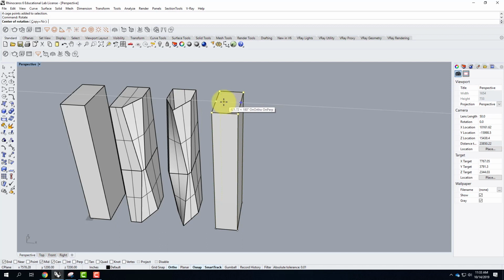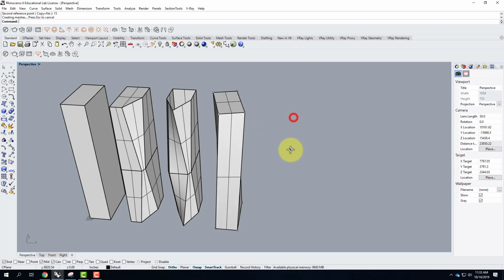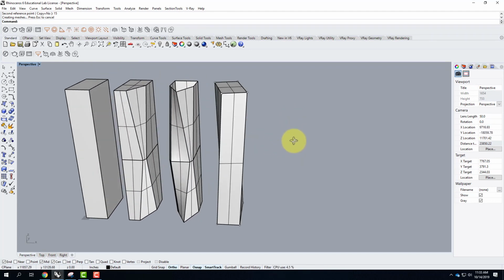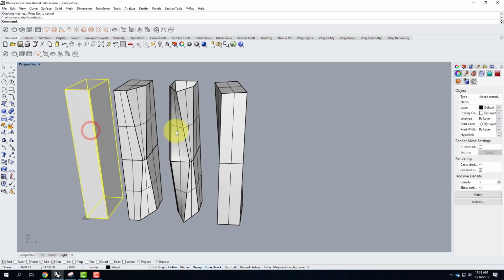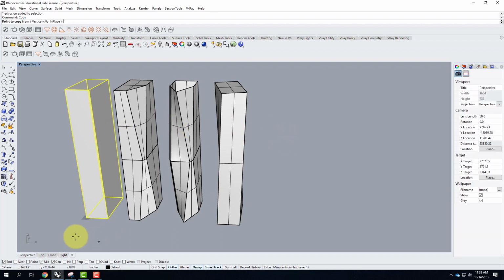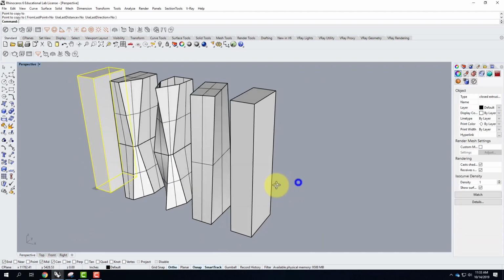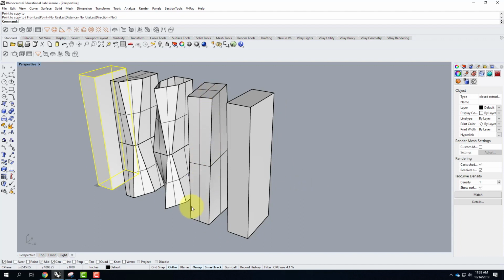Doesn't like me. Let's go over like that, and let's rotate this whole top by, say, 15 degrees. And so that then manipulates this shape by 15 degrees, and it causes that building to twist. Let's take this, and let's explore what some of my other options would be. So in this case, the sides just stayed straight.